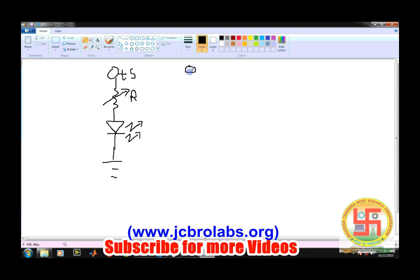For the receiving end, we have connected a photodiode in reverse bias mode, and the symbol for a photodiode has the arrow pointing inwards. This is R1 and this is plus 5 volt. We are taking the output from here. The IR LED and the photodiode are connected in such a way that both face each other in the forward direction.